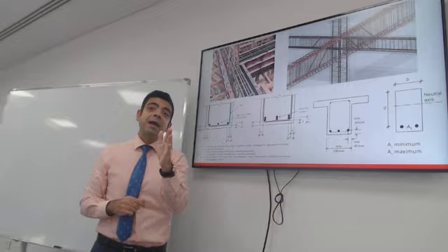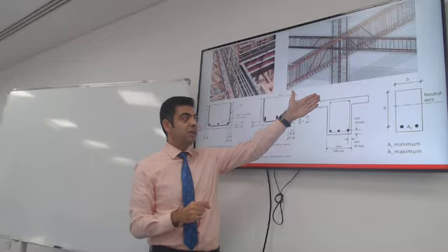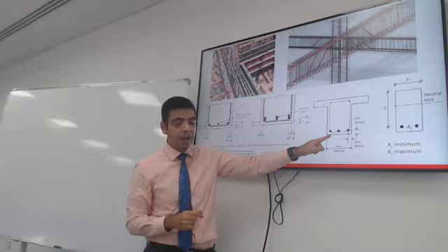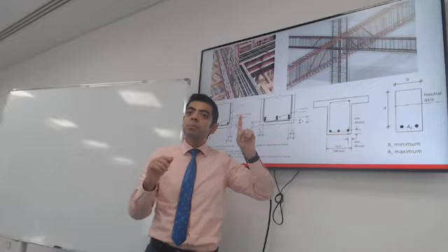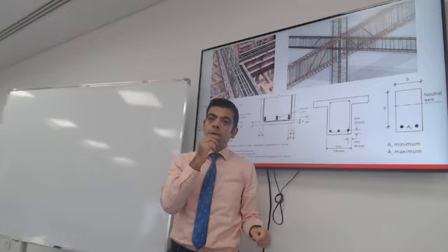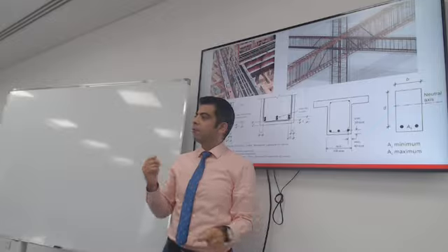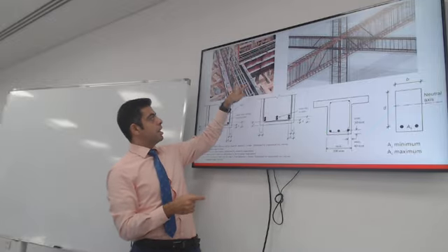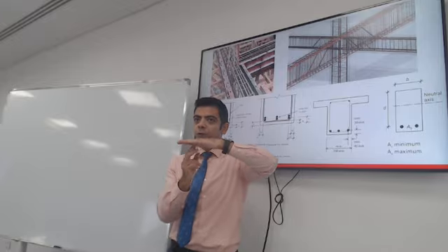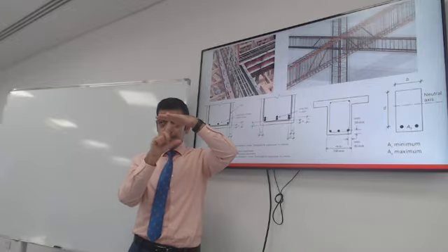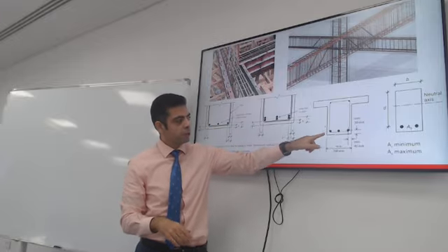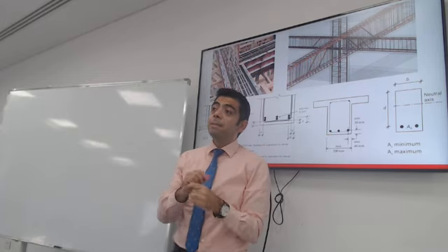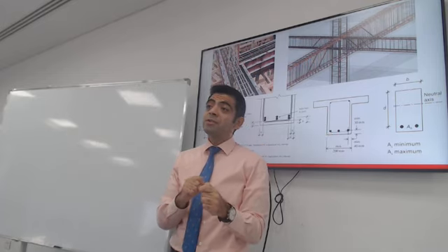So if I ask you to draw the detail of a cross section of a beam and you put the bar right there at the edge, this is completely unacceptable for so many reasons. If you're building the structure and you put the rebar right there on the formworks and you don't leave a spacer for concrete to fill underneath the bars, you're causing big harm to the section.